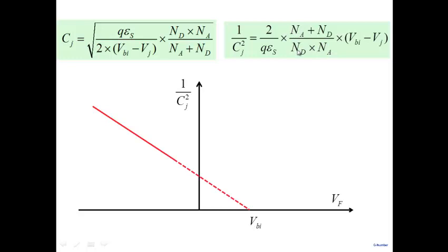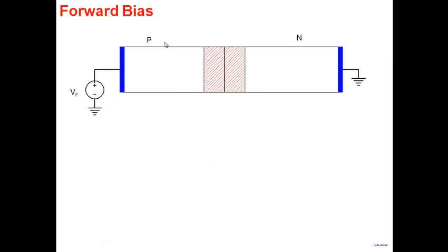And therefore, you can measure the doping of the lightly doped side. Na cancels and you get Nd, and you're able to measure the doping from the slope. So capacitance versus voltage characteristics are very commonly used as a characterization method to measure VBI and to measure doping. And the origin is this particular expression here.